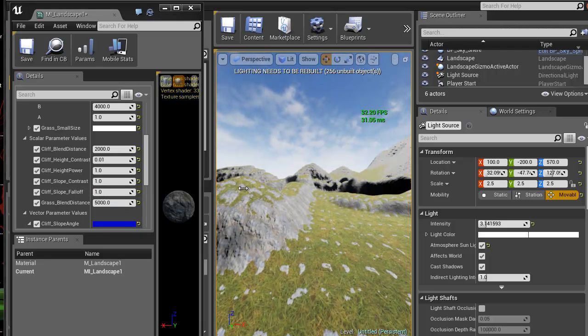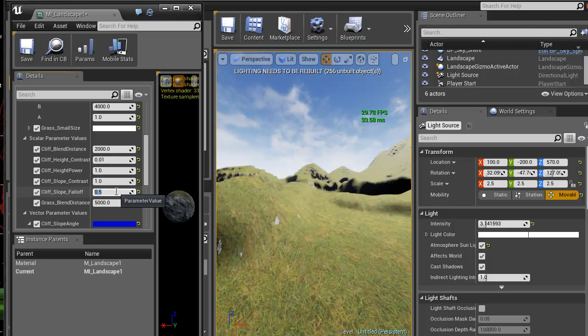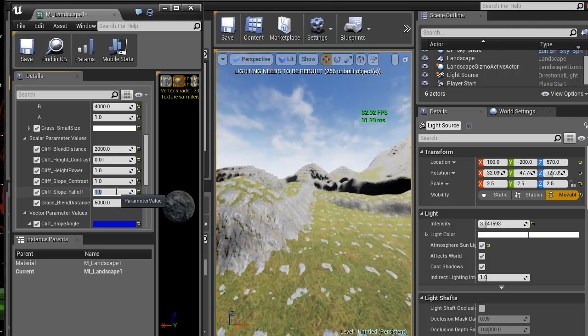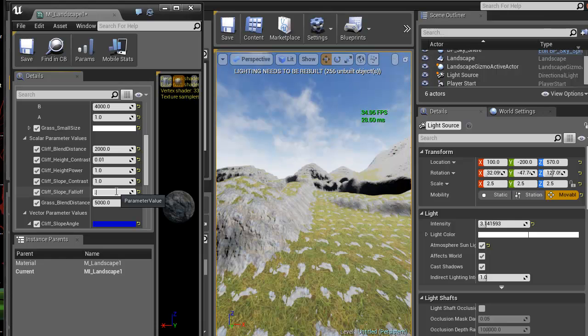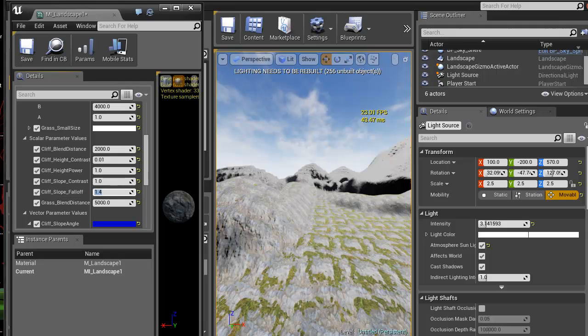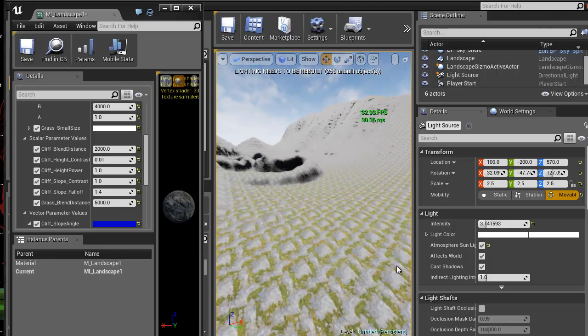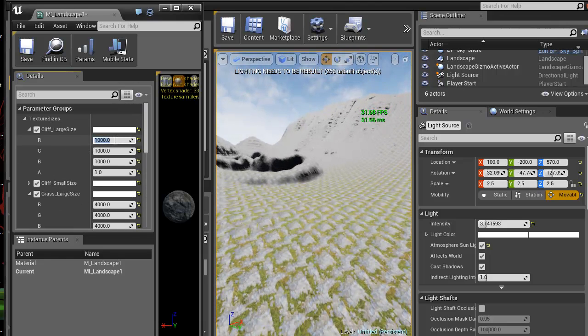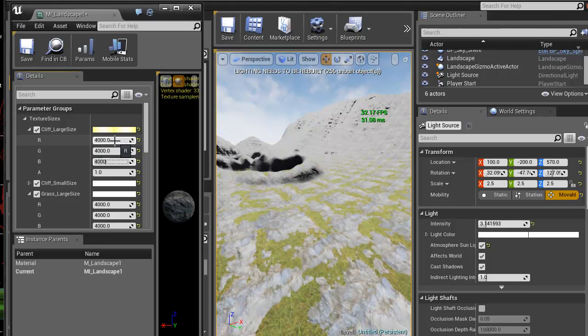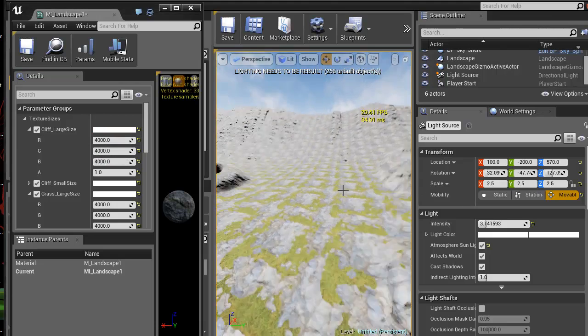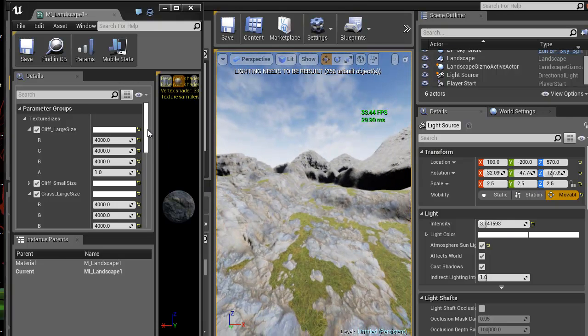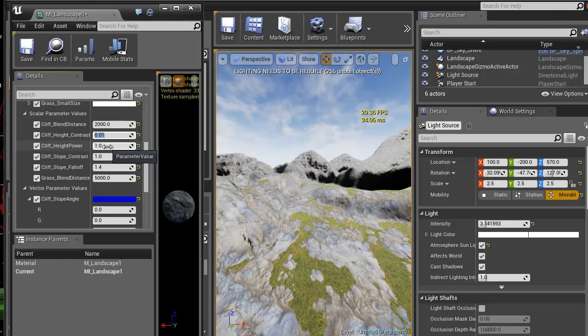So this is going to control the slope falloff, it's going to control the overall slope. Okay, the more I do that, again, 1.01 is going to go 1.1. It's going to start going a long distance here. Okay, you can see that that's breaking up based on my rock, my large rock texture. Okay, so it's going into the height map of that rock. Okay, that's the contrast there.